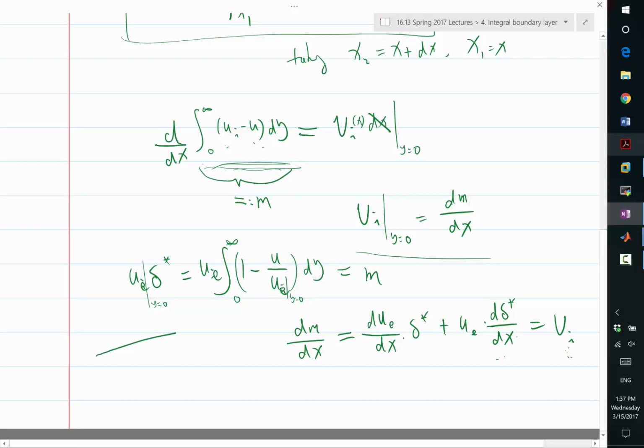So you have a boundary layer that grows like that. This is the wall. The boundary layer grows like that. And your inviscid equivalent flow goes out of the boundary layer at such an angle, Vi and Ue, right? So Vi over Ue in this case is actually the angle at which the displacement thickness grows.